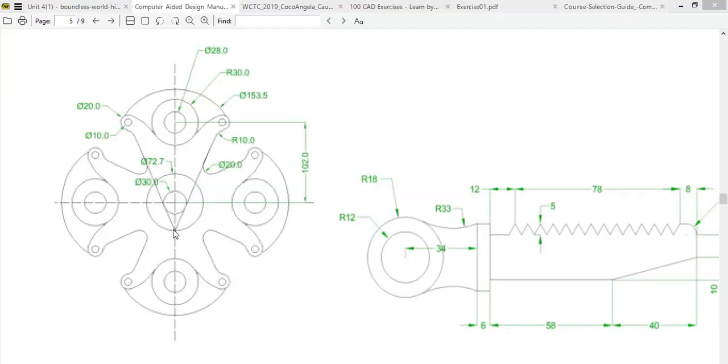Now if I look at this line here, first of all I can see symmetry. Whatever is on the right side of this object, this sub-object, is the same thing on the left side. And you can see that this form repeated itself 4 times. So what I need to do is to design the first half of this and mirror it to this side to get the full object. And then I can easily use array to create the remaining 3.